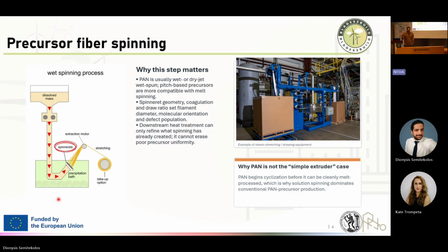You saw an extruder where you put the pellets, and then there was a spinneret where you can extrude the pellets into a fibrous format. So it is based on melting the polymer and producing fibers out of it inside the spinneret. Okay, this is melt spinning.